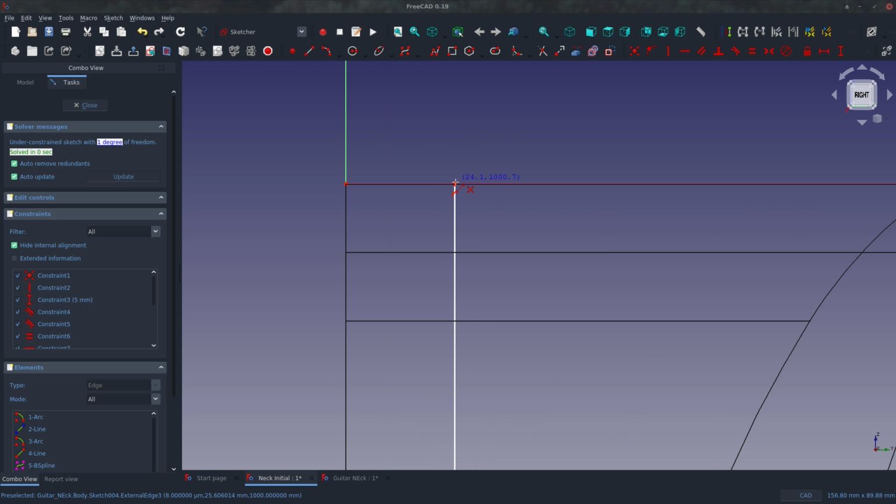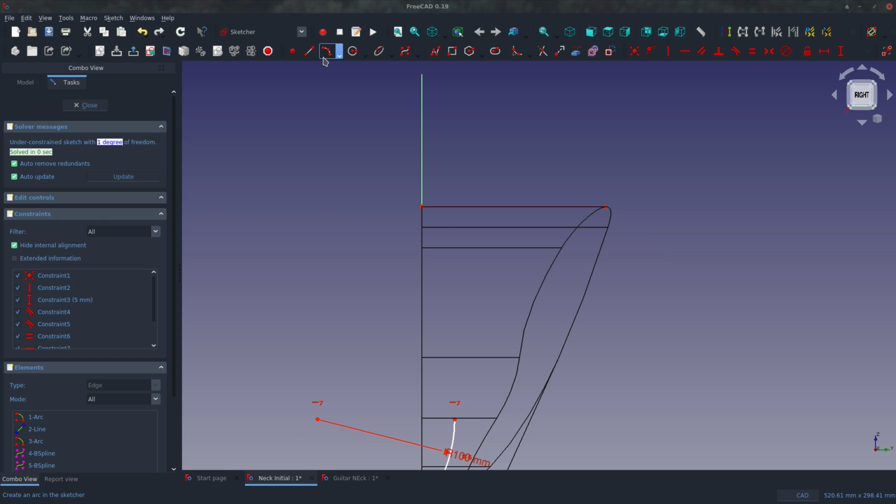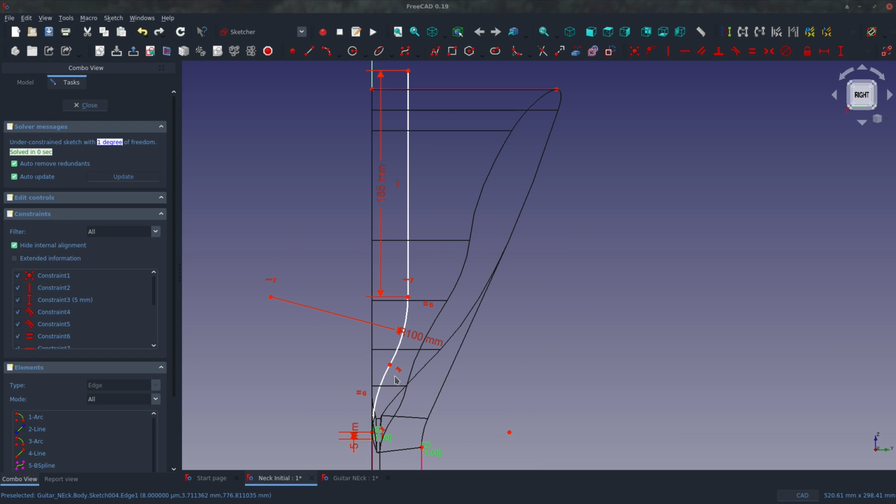Now, maybe this is getting it to be a little bit more zero thickness-ish. So, just to avoid even a possibility of zero thickness, we'll make a vertical line that goes past this. And I think that should resolve it, at least reasonably well. Highlight this line, Shift V for distance. Let's go down to 165. And then maybe I need to constrain this, right? So we'll select the height of just this arc, Shift V 45, right?